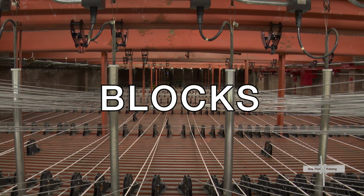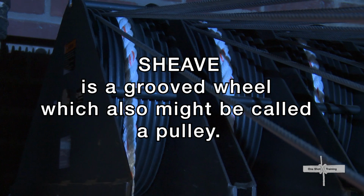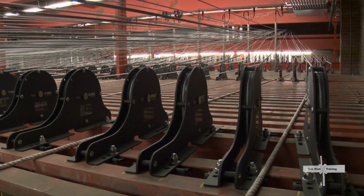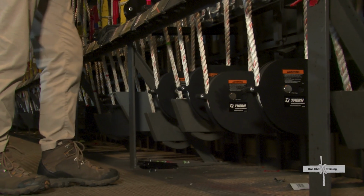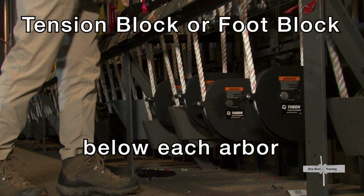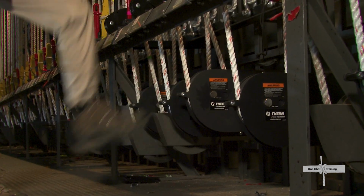Finally, blocks. A block is an assembly with a sheave. A sheave is a grooved wheel, which also might be called a pulley. A fly system has several different kinds of blocks. We use them to guide the movement of both wire rope and fiber rope. In a typical fly system, you'll have a tension block or a foot block below each arbor at the bottom of a rail. We can adjust that to maintain the tension on the operating rope.